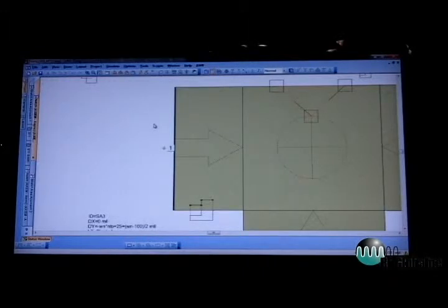The next significant improvement in Axiom is the ability to parameterize an electromagnetic structure directly without having to have a circuit schematic in control. So here we have another simple microstrip T-junction. The reference plane de-embedding is something you should be familiar with from Axiom, but things like these shape modifiers, which allow us to specify inset, outset, notches like you see up here at the top, this is all new stuff for Axiom, and it gives us the ability to have an electromagnetic document be a freestanding document.